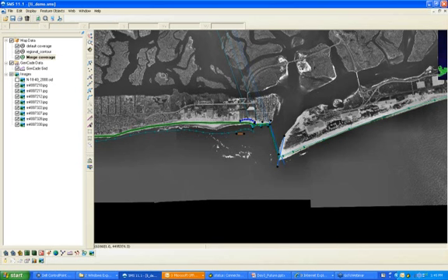We may want to have additional detail here. So in order to do refine points, we can do this in one of two ways. We can click on Create Feature Point, and for this case, I'm going to have 2 refine points. I'm going to list them here and here.